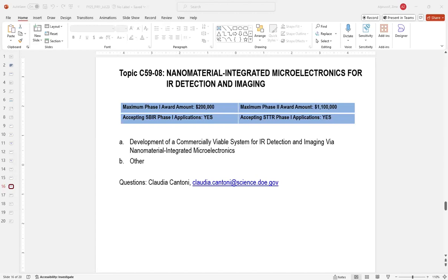And then for phase 2 deliverables, we're looking for a prototype of a sensor that uses these novel nanoparticles integrated with a silicon CCD that can acquire digital image from incident IR and then have the detection by the silicon. So this could include a smooth film of these novel nanoparticles integrated with a 2D silicon CCD.